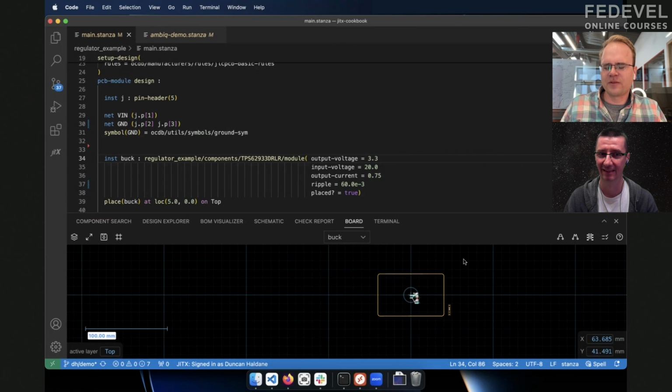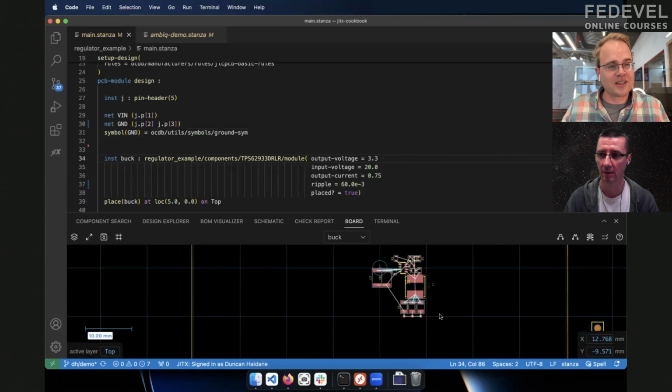This was designed for, I think it was, how do you design a voltage divider that can go to space, right? Where you have temperature swings between -40 and 90 degrees. You need to make sure that this voltage divider on your reset line doesn't reset your satellite every time it orbits the planet. So you start needing to use 0.1% tolerance values and considering that whole stack up at once. So it turns out when you do that, you can just kind of do every voltage divider. It might be overkill, but you know it's done.